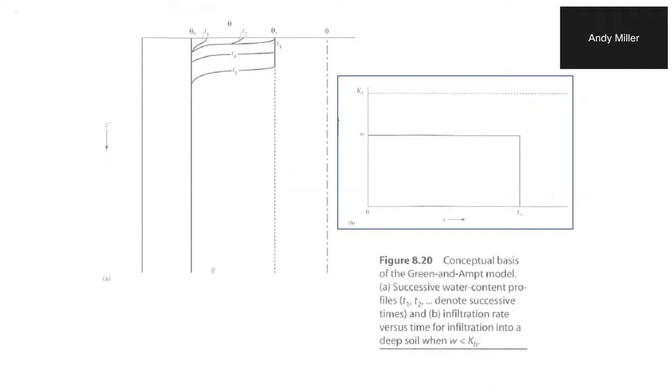It's possible. Yeah, because if it's not raining that hard, you're not adding that much moisture to the soil, but you add enough that the hydraulic conductivity is just enough to transport that downward without having a higher moisture content. That's a real case. You can solve for that. We're just not doing it here.